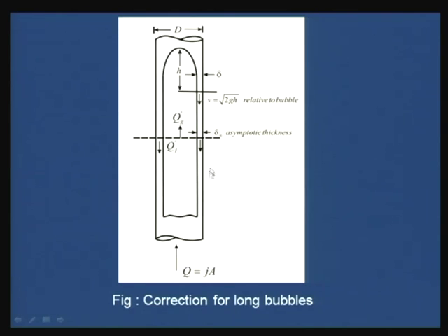If this does not contribute to the pressure gradient, then we can very well imagine that the liquid film here almost behaves like a gas, and this entire surface is maintained at constant pressure in this particular case, isn't it? So, therefore, actually the alpha should be calculated from this particular expression.